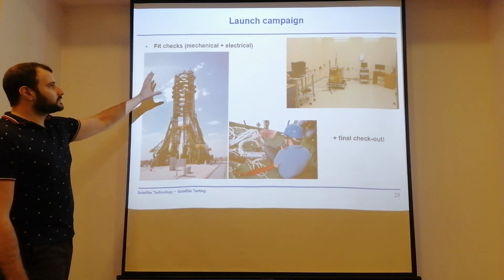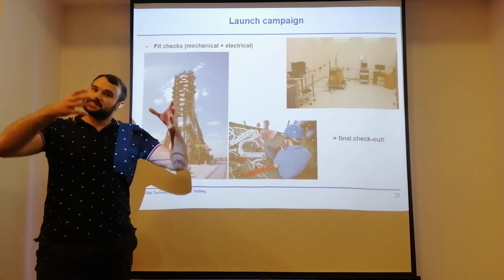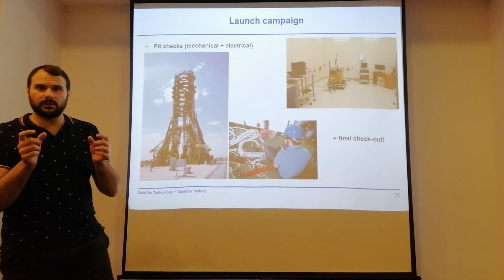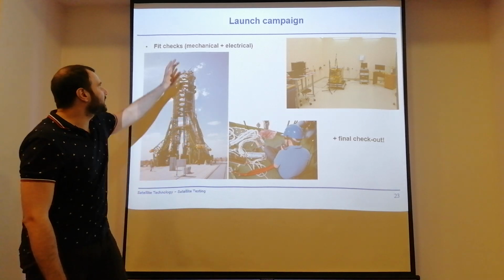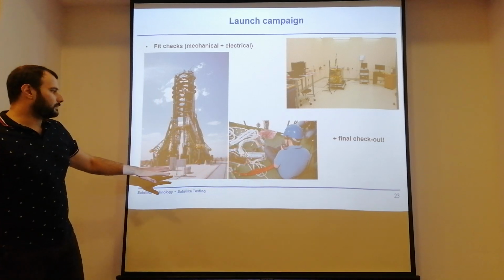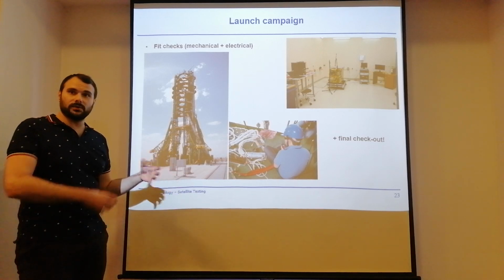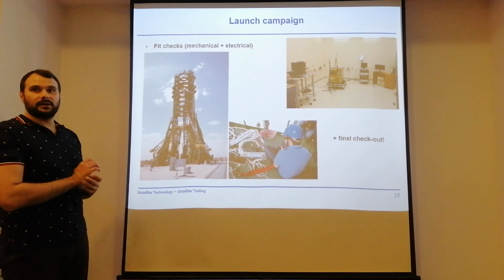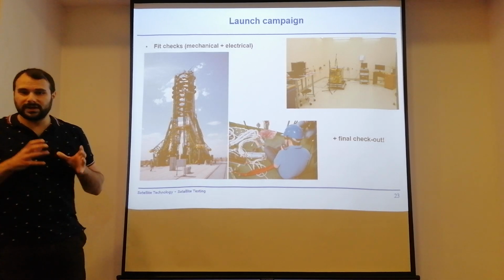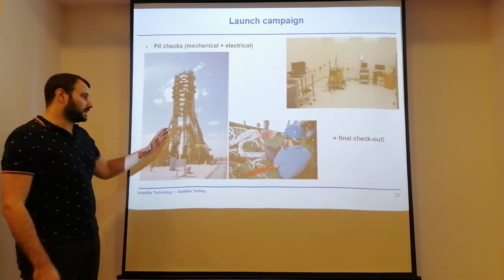Lastly, there were some fit checks to be done, mechanical and electrical fit checks. So there were some tests performed if the satellite would actually fit into the launcher bay for a rideshare mission. So the clearances are all there to the other satellites. This is the mechanical fit check, but also the electrical fit check. You can see here, in our case, we had to charge the satellite even once it was already installed inside of the Soyuz rocket. So in the morning of the day of launch, we connected lastly our battery chargers to our satellite to charge the batteries before putting it into space.